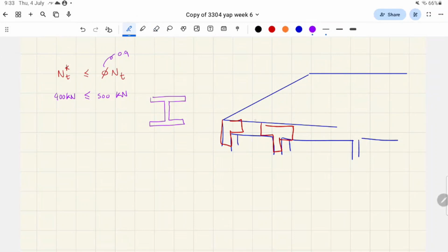The idea is that the loads have to go somewhere, and so they transfer from the slab to the beam, and they transfer along the path of least resistance. So it goes like this. Just think of it like every electron has to be accounted for in terms of the self-weight and the loading.